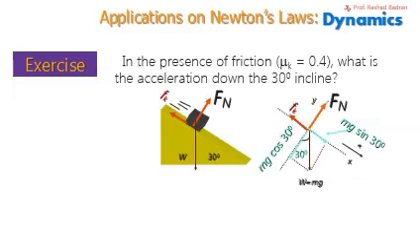And this force of friction is nothing more than the product of the coefficient of kinetic friction, which is given in the problem, and the normal force. Now the first step is to set up the equation along the x-axis. That is the net force, which is the product of the mass and the acceleration along the x-axis.